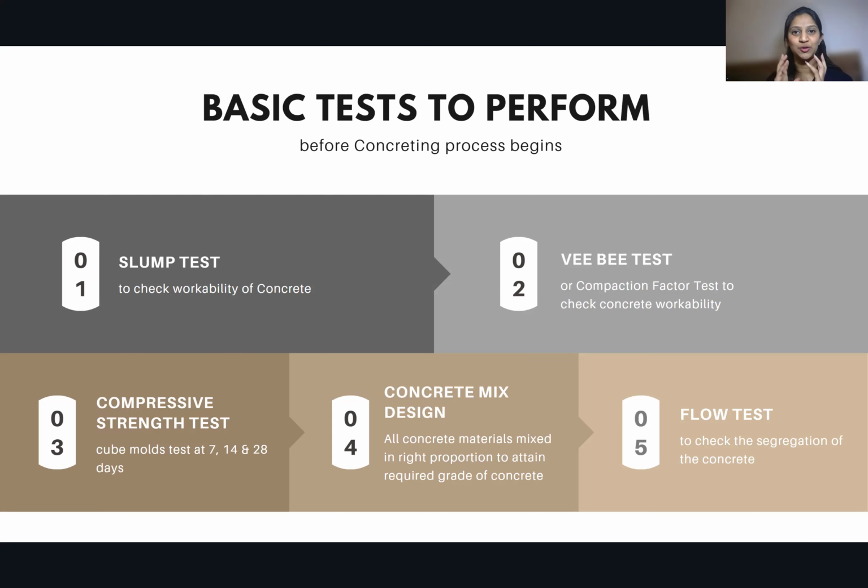Over here, it uses the actual materials with nice quality, all the aggregates, all the cement, all the fine aggregates, along with the proper proportion of water. Everything will be tested at 7, 14, and 28 days. And the compressive strength will be tested with the compression testing machine, the CTM machine, and only then will that particular mix actually be taken into the picture. What is the maximum load that this particular kind of concrete can take? That is the compressive strength test performed for concrete.